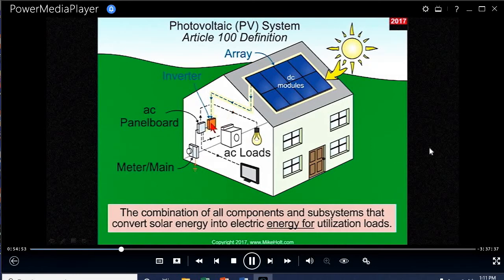Yeah, I probably should add another graphic on top of this one, Brian and Mike, showing that it comes off of that breaker. When you come off of that breaker and you supply the PV system, that's where the PV system actually stops, and it includes the breaker that you're connecting, actually connects right here, to this enclosure right here. So it includes all the parts, including the breaker that you terminate in or the line side connection. In the book, we'll probably add a couple more graphics to enhance that. But we're going to cover that in 690 anyhow.